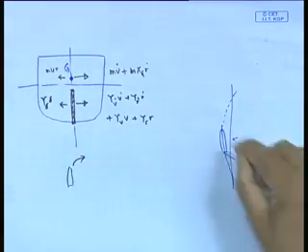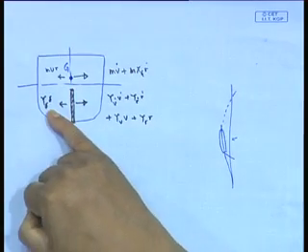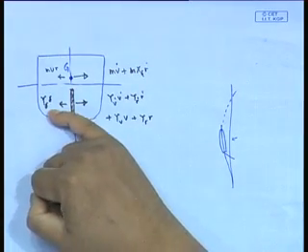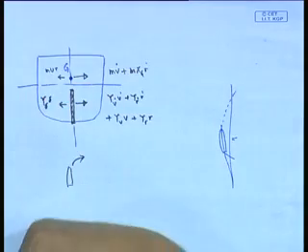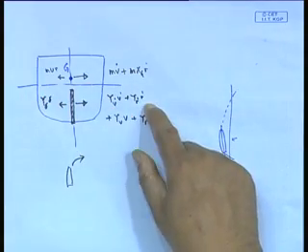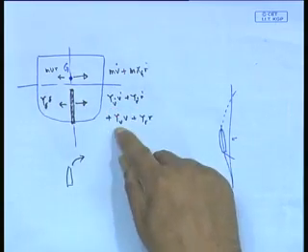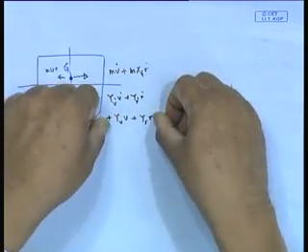Now, what happens in the initial phase is that I gave a large y delta initially, because I just applied the rudder. My v dot and r dot are small values, and y v dot, y r dot is typically smaller than this, and this force is represented smaller than this normally.